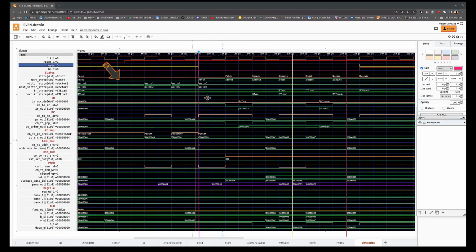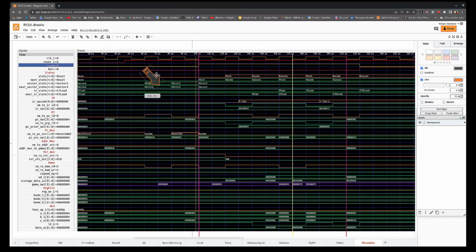So here is the simulation, and sure enough, our flow has been interrupted and shortened by one cycle. You can see that the RT complete is no longer present and that the cycle count is much shorter. So the short circuit is actually working. We've added these two values, but the X3 register still has the value 8 all the way through. We've done nothing. This is equivalent to a no-op instruction. We've arbitrarily added two values together, but we didn't store it anywhere. And that's what we expected, so yay!